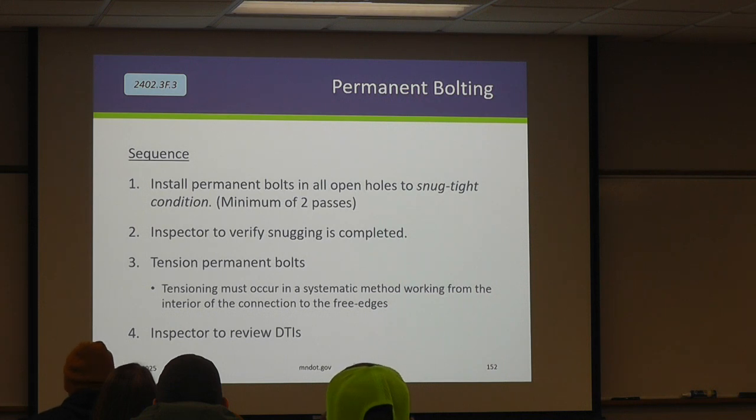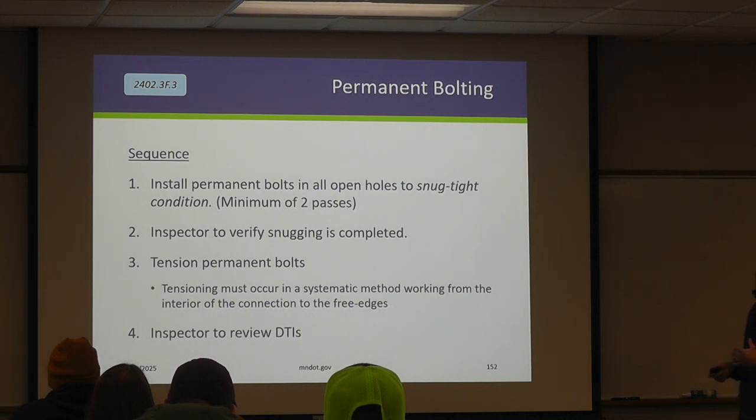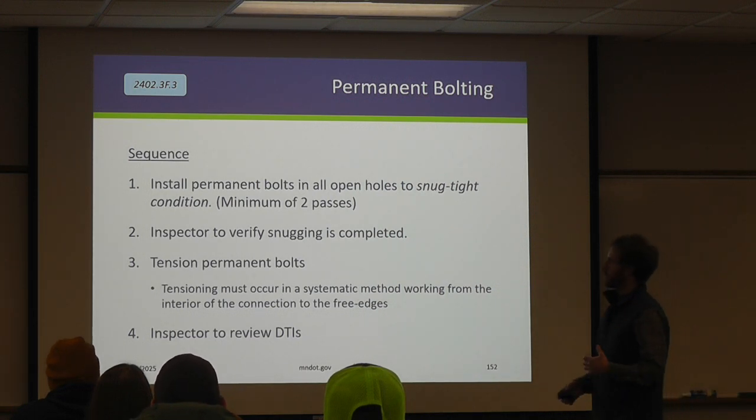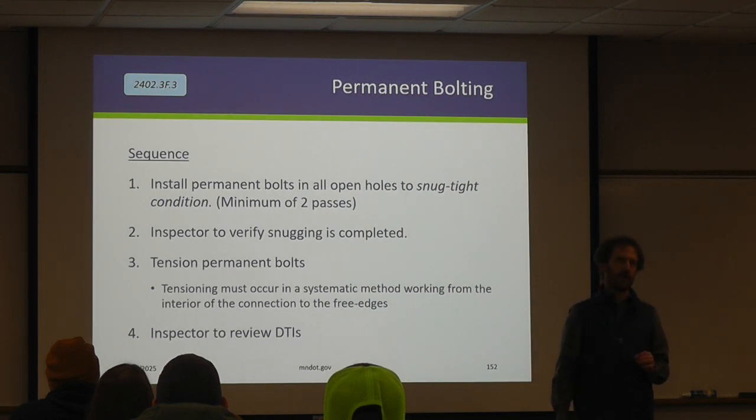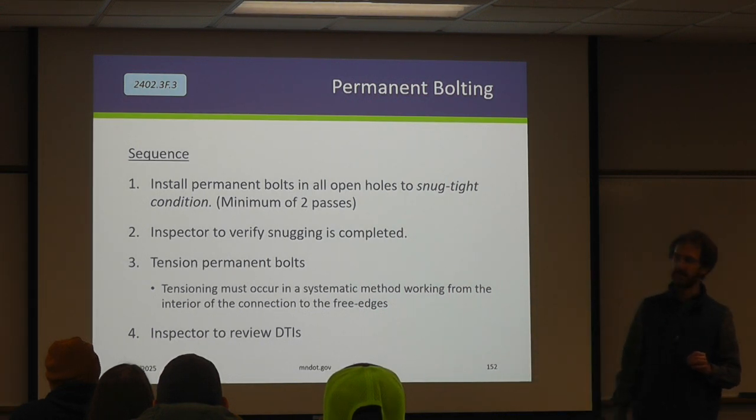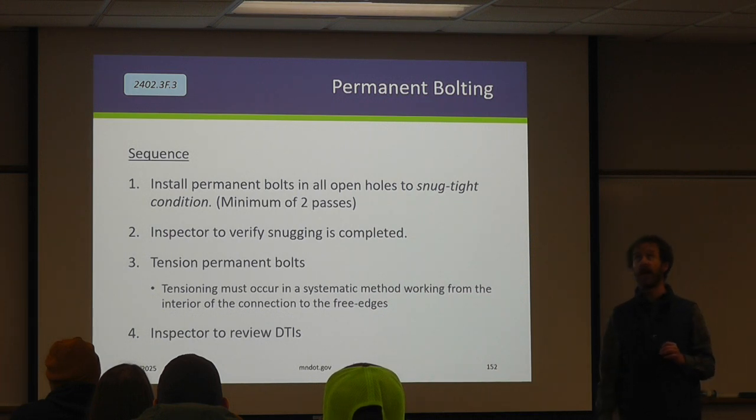So, how do we properly tighten a bolt? This seems very silly on the surface, but this is really important for these bolts to function the way they're intended. So you've installed all of your permanent bolts to a snug, tight condition. Snug tight is a very challenging thing to define. Our spec book, I believe, defines it as the ordinary effort of an iron worker.